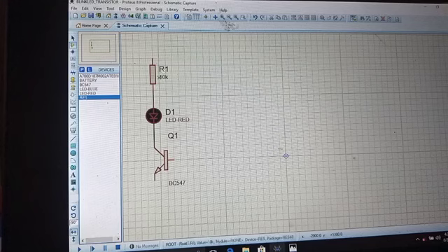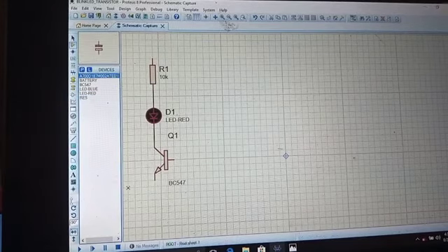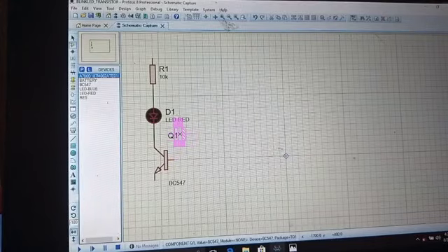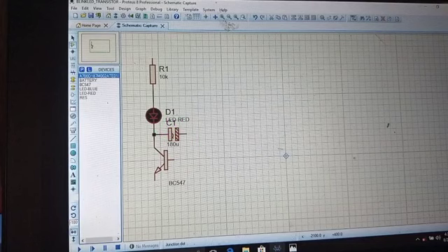So when you connect it there, you see how it is linked together. In case you drag to a wrong position, you just press escape to cancel the line. Yes, so when you click the component, you bring it like this capacitor. When you bring the component, it is pink, something like a pink or purple like that.